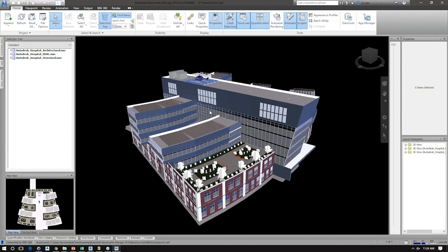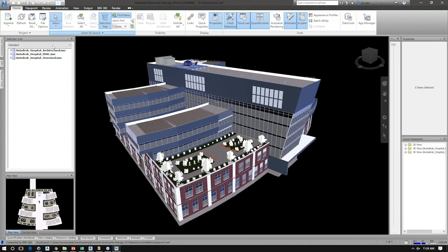So let's talk a little bit about just selection and understanding and viewing our model inside of Navisworks. One thing I'd like to point out initially is that something that most people get hung up on is understanding the way that Navisworks selects elements. By default, Control-1 always allows me to bring up my selection arrow, right? You'll see that if I hover over that tooltip, I get my select Control-1, and I can either select via a pick or a selection box. And there are various ways to select elements within Revit based on a hierarchy, right?